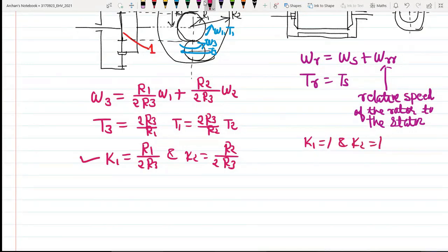Okay. So just like the torque coupling device, the speed coupling units can be used to constitute various hybrid electric drivetrains. Okay. So we may see the hybrid electric drivetrains with speed coupling of a planetary gear unit, or we may have a hybrid electric drivetrain with speed coupling of an electric trans-motor. Okay. So these are the possibilities in which we will be able to connect the speed coupling, right?